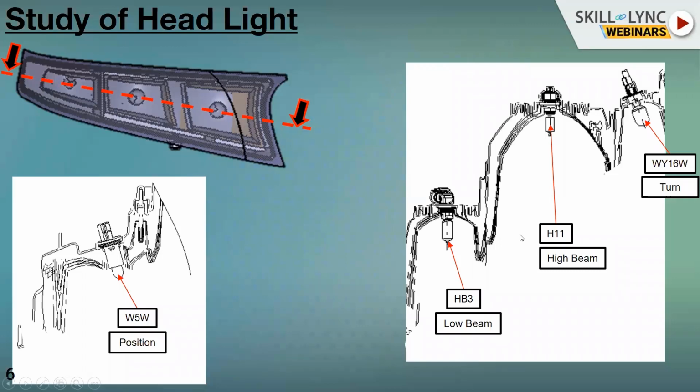However, there are many other BOP parts involved in the headlight, like the dust cap and the aiming bolt, which helps to rotate the reflector manually, and many other parts: wire harness, and sometimes you have to use the desiccant bag, the vent cap, the Goretex patch. These are the basic requirements of the headlamp. There are almost 40 to 45 BOP parts, small or major, used in the headlights. We do not have sufficient time to cover them all. However, the basic section is very important for session 2 that we are discussing here.